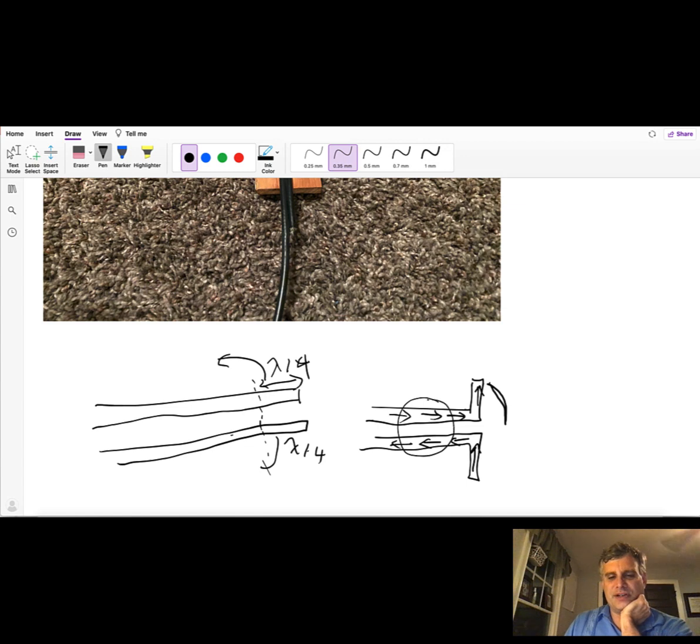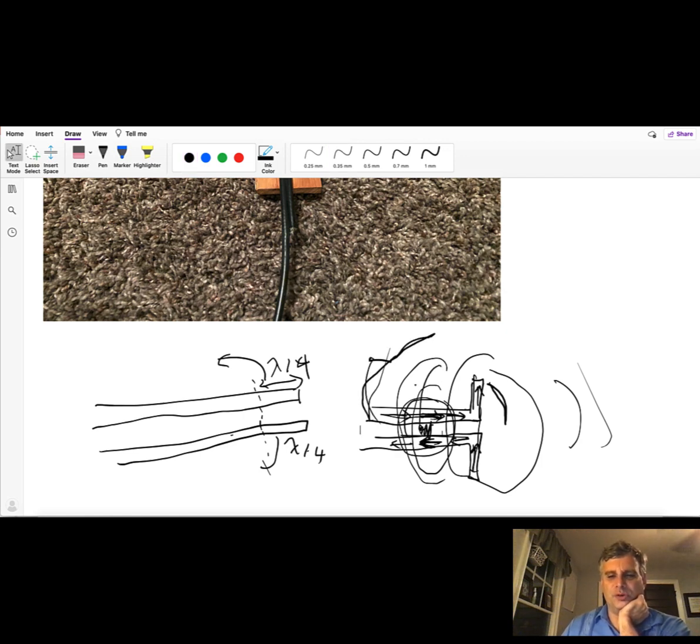Why? These are confined currents. In other words, if I've got a current this way, I've got the equal and opposite current right next to it on the transmission line so that there's not going to be any radiation from that structure. It's field confinement mostly between the antenna feed elements, the wire that feeds the top bar and then the bottom bar. This structure over here, however, is different. I don't have that destructive cancellation. Instead, these currents, when I bend these back, are doing the exact same thing in the exact same polarity. And so this geometrical structure is capable of launching far field waves.